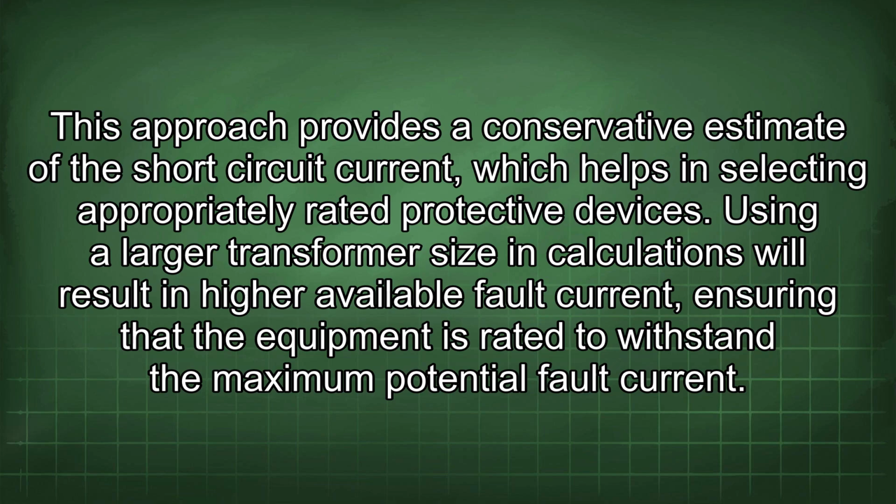Using a larger transformer size in calculations will result in higher available fault current, ensuring that the equipment is rated to withstand the maximum potential fault current.